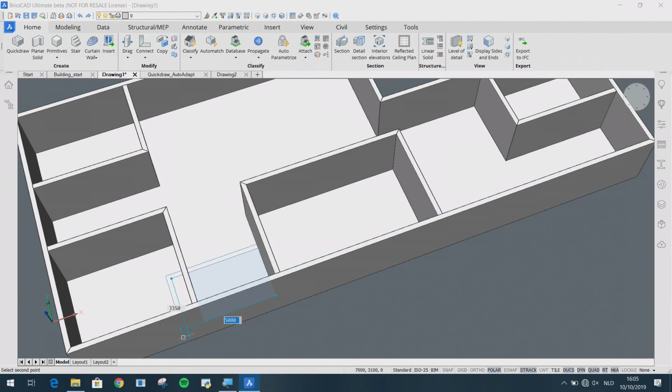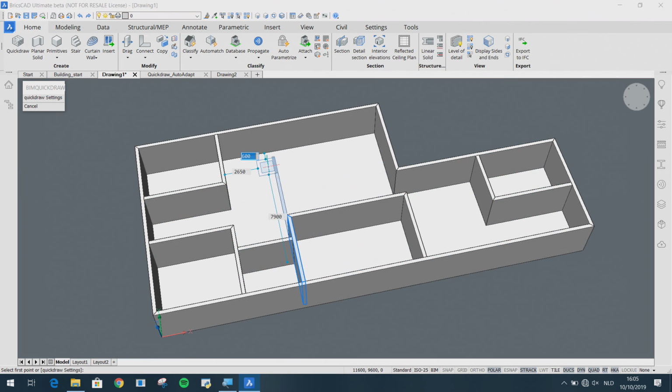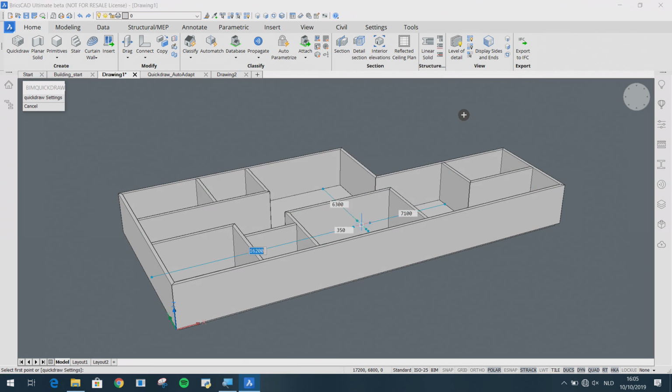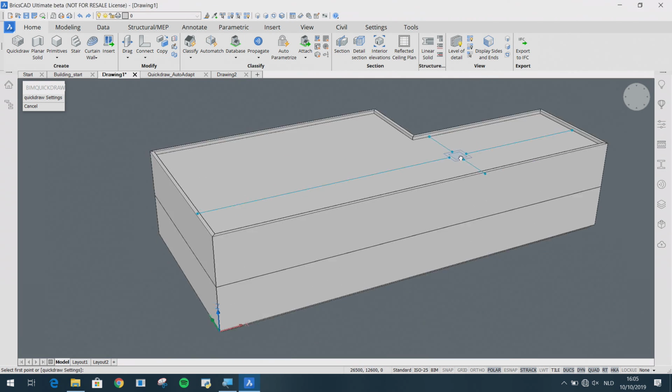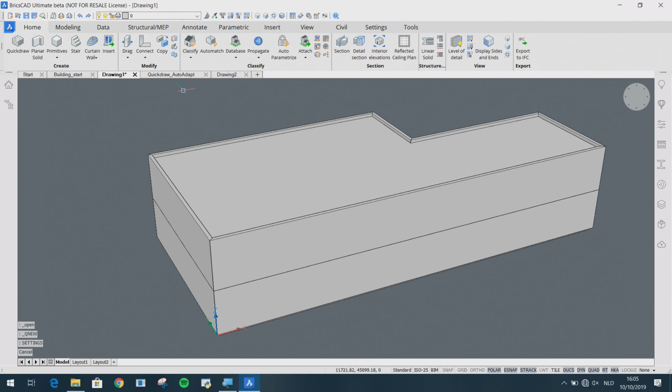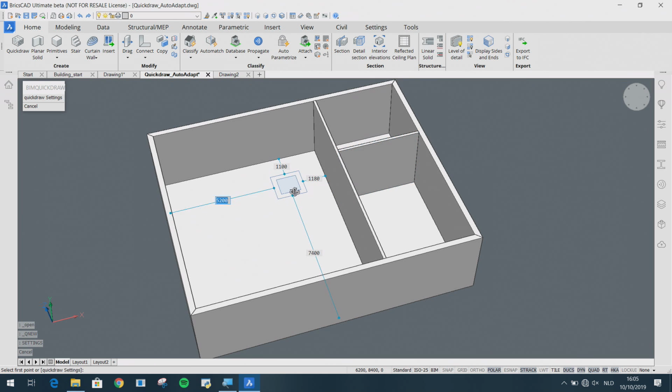As you can see, the room cursor exhibits a snapping behavior. It snaps to existing walls, also to extensions of existing walls, such that you can really easily align your walls in your model. And then you can quickly add some extra levels and maybe finish off with the roof. So what we have done for V20 is to extend the snapping behavior of this tool.